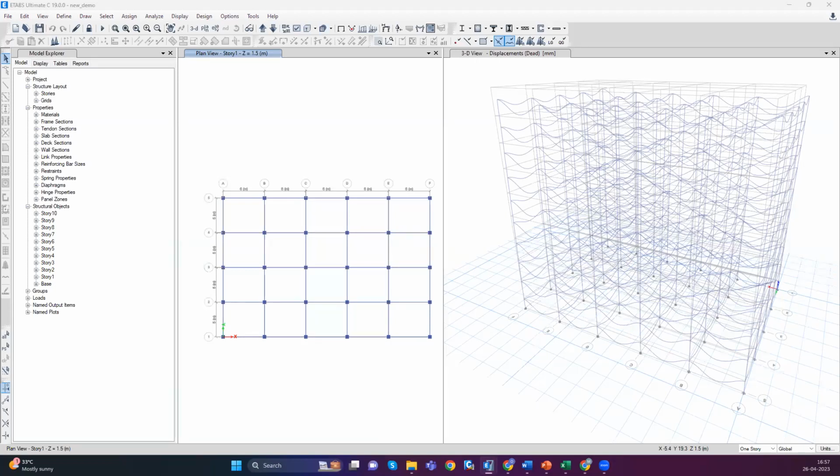It says 0.5 times the effective depth of your cross section plus 0.05 times of section modulus. And section modulus also you can approximate to 0.5 times the length of the beam, right? So where this LB is the distance from the hinge to the point of contraflexion. So with that formula also, one can easily calculate the plastic hinge length.